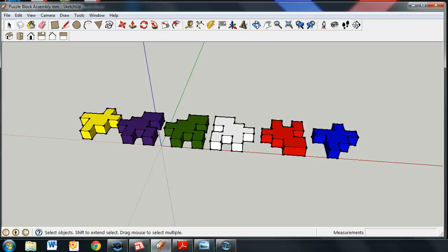Now we must take the SketchUp model of all of the pieces that you see right here, and we're going to convert them into a STL, or a surface tessellation file, which basically records all of the geometry of each of the pieces. Okay, so you will actually be able to record all of that data in coordinates, and you will be able to take all of that, convert that into the STL format, which will then be able to be understood by the Makerware program or any 3D slicing program that is used with the 3D printer at your school.